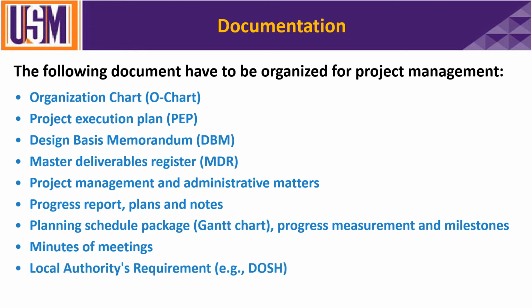Then you will have the local authority requirement, for example, DOSH, Department of Safety. So for pressurized vessel, if you have a pressurized vessel, you will need to report to DOSH. They have to come and inspect. Even if it is not pressurized, they say DOSH, even if the reactor is 6 inches and larger, you need to report to DOSH. So if you want to avoid DOSH, you are operating not pressurized, but you are operating too large, you still report to DOSH. You need to have at least a 4-inch reactor, so you don't report to DOSH.